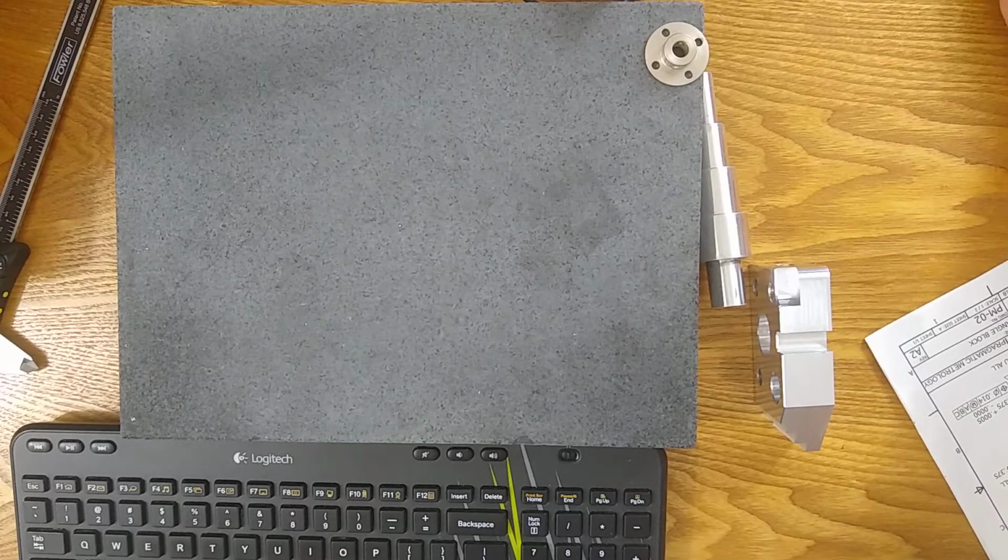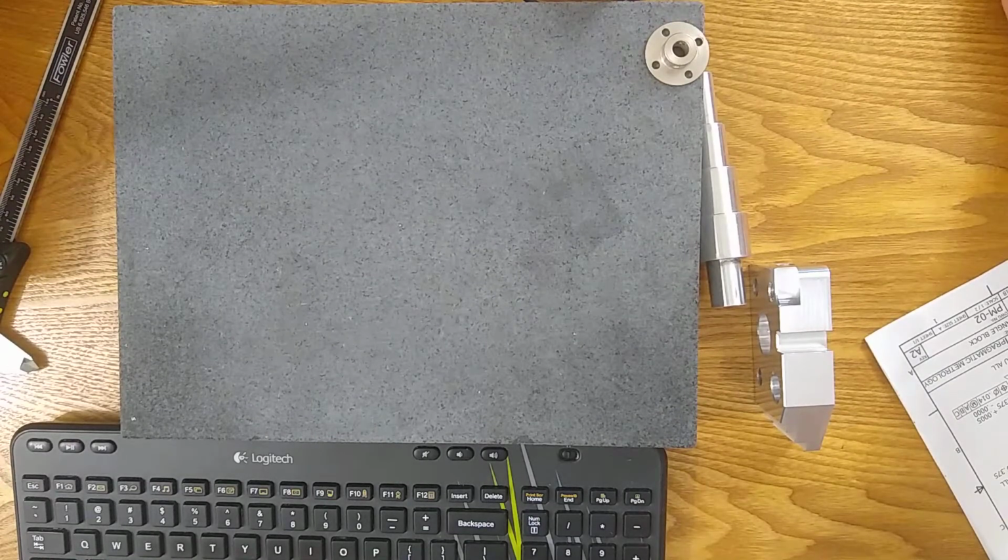Whenever you see this frame, it'll be a rectangular box, and it'll have a symbol. This is the GD&T symbol for position. It will then have a box with the tolerance. In this case, the tolerance is a diameter of 0.014, so it's a circular tolerance. You get a modifying symbol sometimes, which will be an M or an L or many other symbols. Actually, I don't know if other symbols go in here off the top of my head, but this one means maximum material condition. And then you'll have your datums: datum A, datum B, datum C.